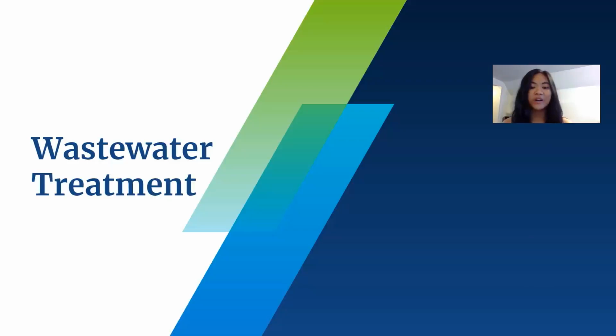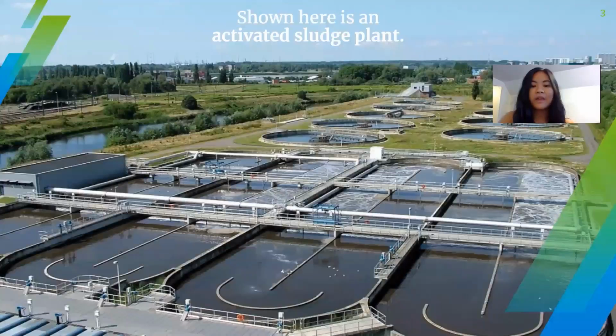Biological treatment processes are some of the most effective ways of reducing matter derived from living organisms in wastewater. One of these processes is called the activated sludge process. The activated sludge process uses highly concentrated microorganisms, mostly bacteria, to degrade organic matter from wastewater. Wastewater treatment plants take influent water containing organic material from humans and animals and use the activated sludge process to treat it. The result is a high-quality effluent.